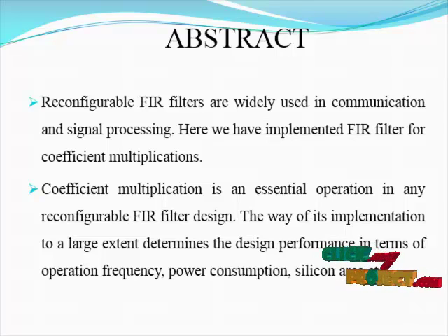silicon area, etc. Common subexpression elimination was initially proposed in order to minimize logic resource utilization by removing some redundant sets of the computation, though being specific toward those FIR filters whose coefficients are fixed. The CSE algorithm was further explored and optimized in attempts to improve the efficiency in the use of the logic resources.